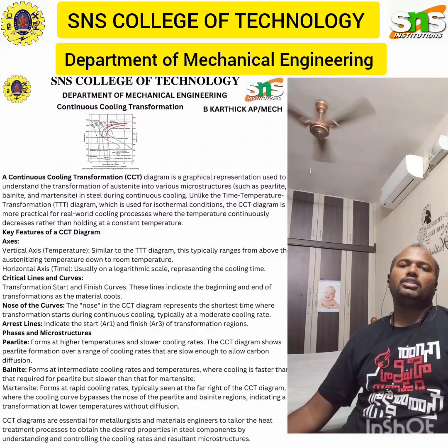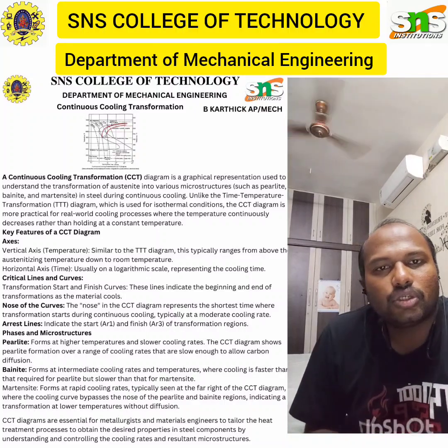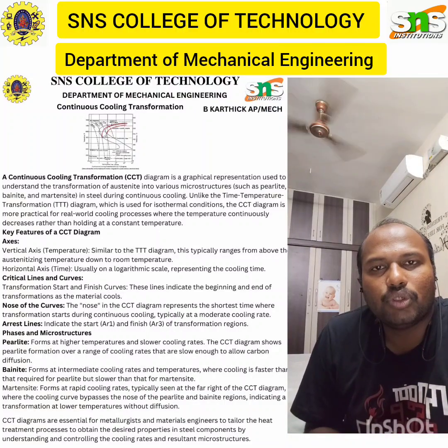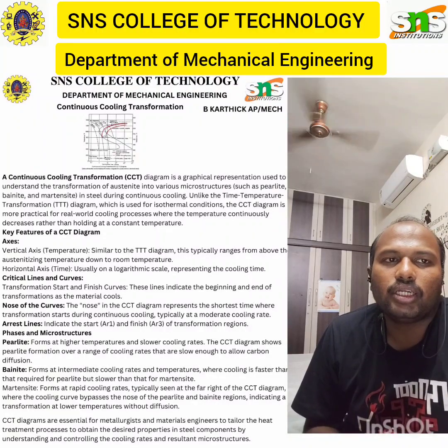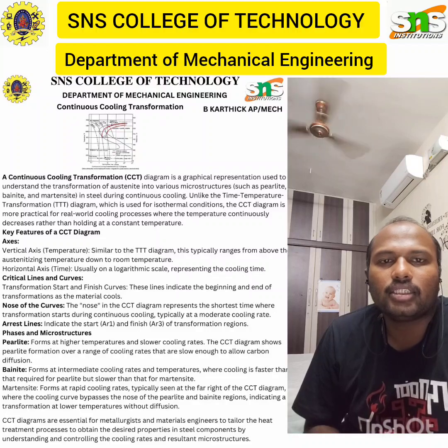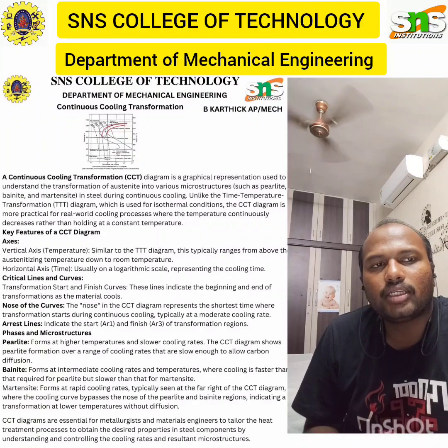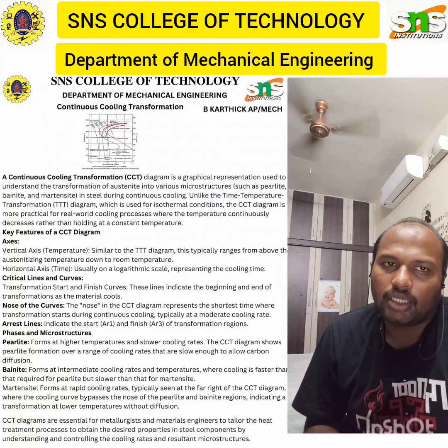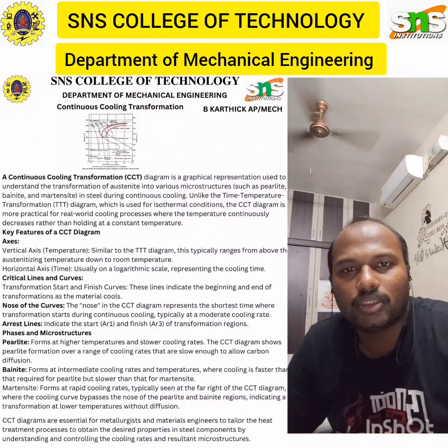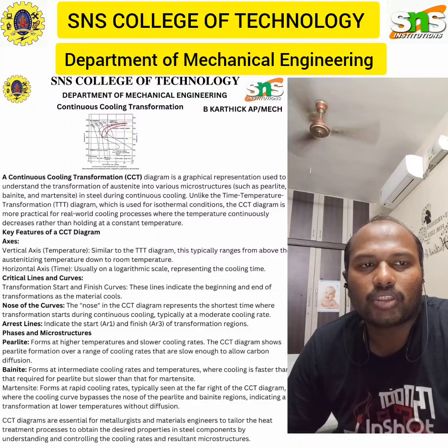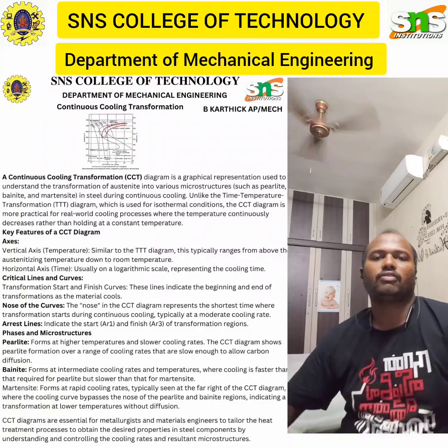So the main usage of the CCT curve is to determine the cooling rate. The cooling rate followed on the CCT diagram can be used to predict the resulting microstructure. For instance, a slow cooling rate might follow a path through a pearlite region, while a rapid cooling rate could bypass the pearlite and bainite region, resulting in martensite. In predicting mechanical properties, the final microstructure indicated by the cooling curve on the CCT diagram helps in predicting the mechanical properties of the steel, and the different microstructures like pearlite, bainite and martensite have distinct properties in terms of hardness, strength and toughness.